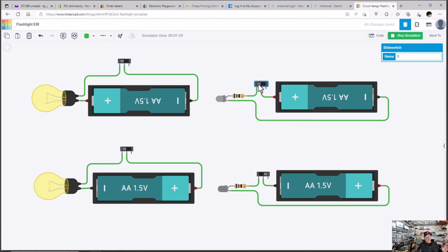So now we'll turn on this one. You see it went light gray, but watch, this one does nothing because the battery's in backwards. That's because this is a light emitting diode, and this has to go to the positive terminal, and that has to go to the negative terminal. It is polarity sensitive. Incandescent is not polarity sensitive. It doesn't care what direction you run current flow through it. The little wire inside of here is going to get hot and light up.